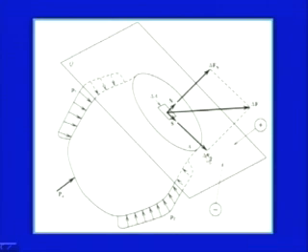Delta Fs is my force which is parallel to the plane, so it is termed as the shear force. Delta Fs is the shear force. So, these two forces are there exactly according to the load application. That is why they are termed as the normal force and the shear force. This can be either tensile or compressive. So, this delta F is the resultant force because of the presence of the shear force and the normal force.